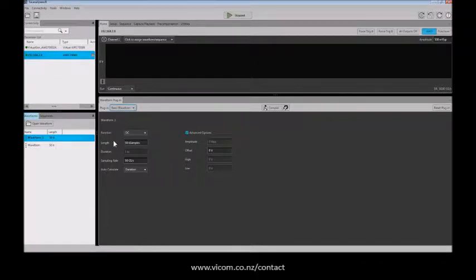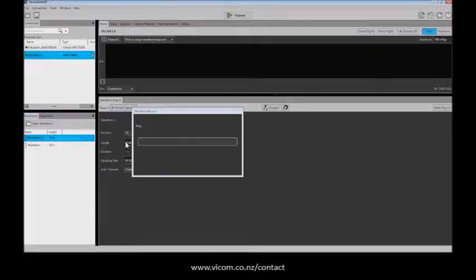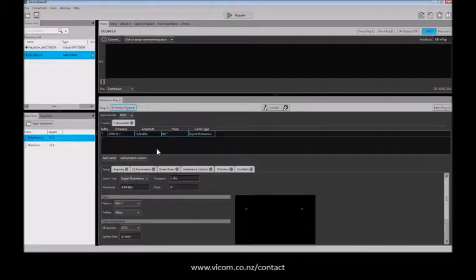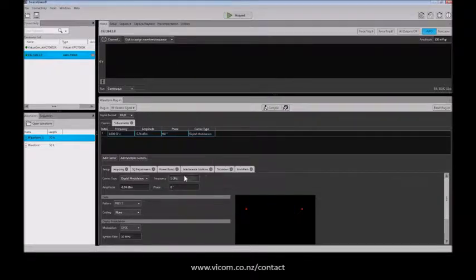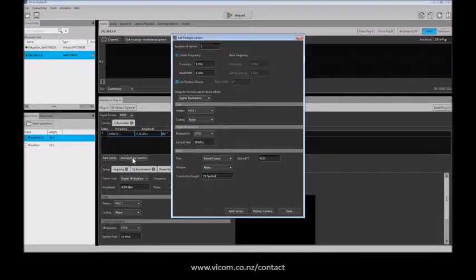Then I go into the RF generic signal generation tool. So the plugin starts, and here there are some things I want to do to make sure. I go to the settings here, and I want to have 50 gigasample manual. Okay. Next step is to add what we call multiple carriers. And we set the center frequency here. This is how I use it, 868. There are different ways of doing this, but 868 megahertz.